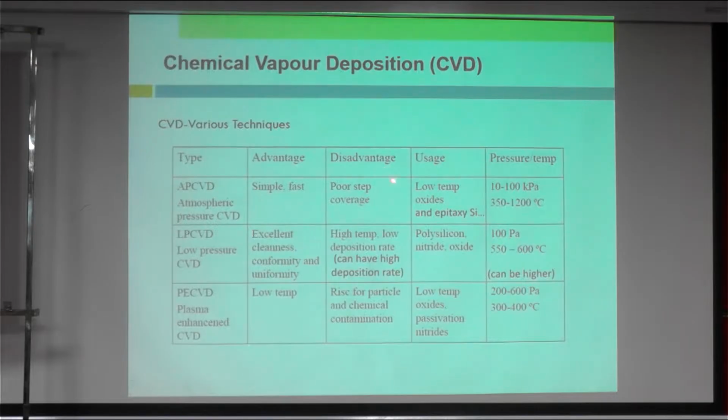So this advantage plus step coverage is something similar to an evaporator. And for LPCVD, high temperature, low deposition rate, but it can have a high deposition rate as well. But there is a risk of particle and chemical contamination in PECVD.